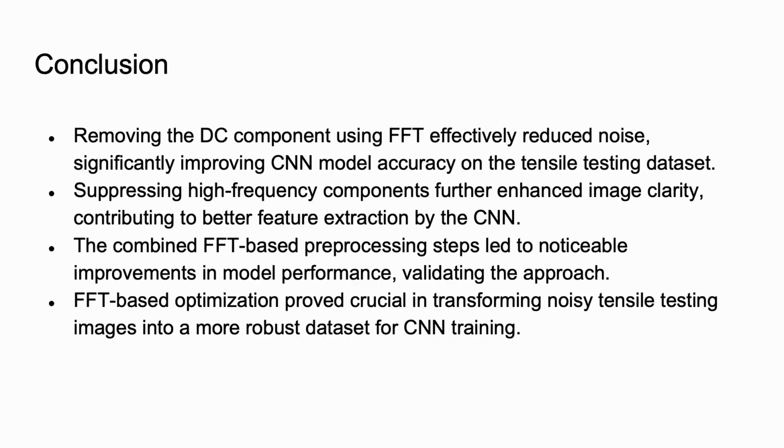In conclusion, removing the DC component using FFT reduced noise and significantly improved CNN accuracy. Further suppressing high-frequency components enhanced image clarity, aiding in better feature extraction. Overall, FFT-based pre-processing proved to be a powerful tool for transforming noisy tensile testing images into a robust dataset for CNN training. This approach highlights the potential of FFT in optimizing machine learning applications for real-world data.